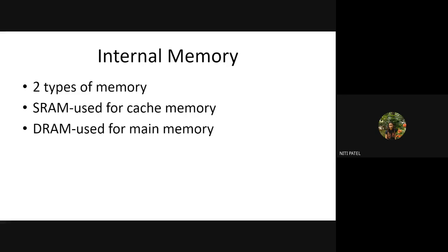We have seen how the contents can be accessed randomly, since the data is stored in the memory cell where we had rows and columns. So every row and column has an address, that is 00 at row and 00 at column. So the complete address is made as 0000. Similarly, for the next row we have 01, and if it is the same column we have 00. So the address is made as 0100. If you all remember that memory diagram which I had drawn in the word.